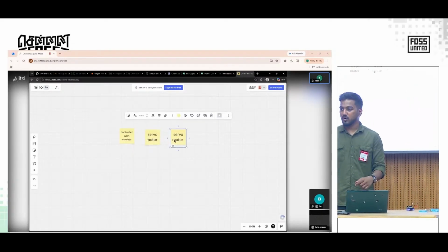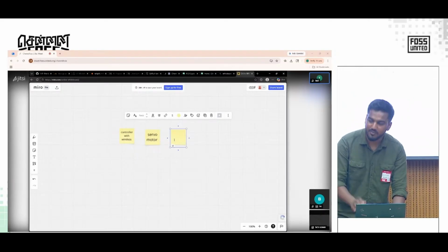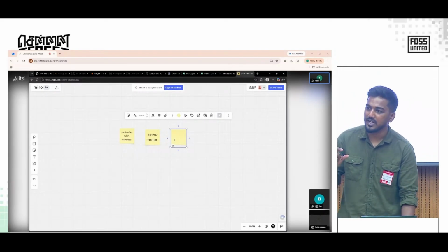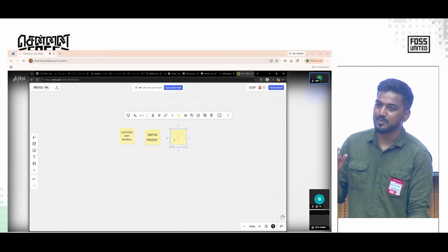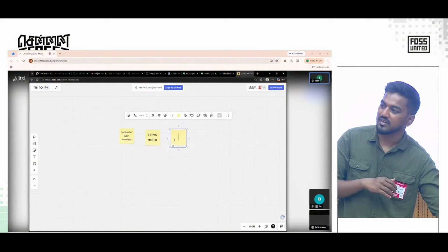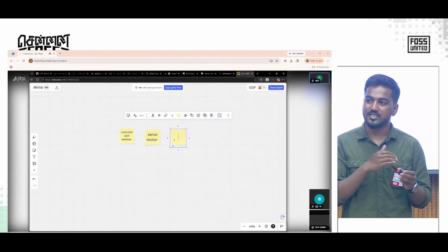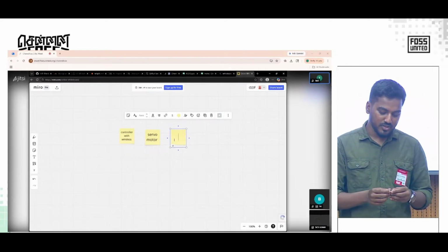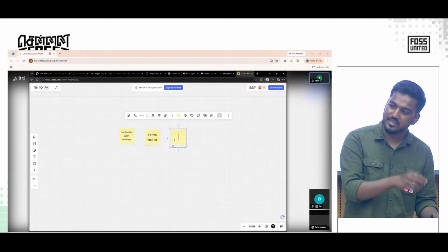And then you need the OLED display itself. You can use any sort of display, but the particular display that we use is called a 1.3-inch SH1106 OLED display. The specialty of this display is it requires only 4 pins for connection. You can get different displays with different communication protocols and different connections to the controller. The reason to choose this is it's very simple to use, and it just plugs in place.